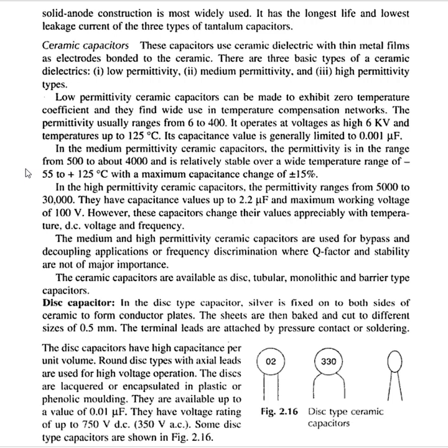In the high permittivity ceramic capacitors, the permittivity ranges from 5,000 to 30,000. They have capacitance value up to 2.2 microfarad and maximum working voltage of 100 volt. However, these capacitors change their values appreciably with the temperature, DC voltage, and frequency. The medium and high permittivity ceramic capacitors are used for bypass and decoupling applications or frequency discrimination, where the Q factor and stability are not of major importance.